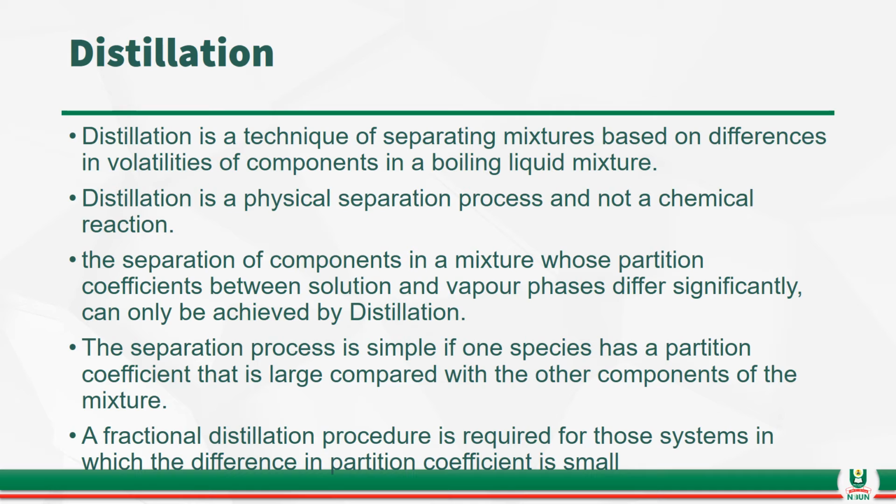The separation of components in a mixture whose partition coefficients between solution and vapor phases differ greatly can only be achieved by distillation. The separation process is very simple if one species has a partition coefficient that is large compared with the other components of the mixture. A fractional distillation procedure is required for those systems in which the difference in partition coefficient is small.